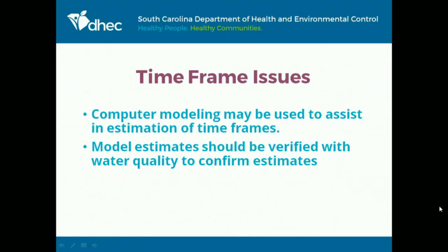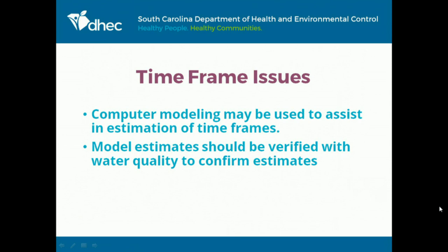Certainly, if you are going to do modeling, I do recommend verification of the modeling with water quality information. So get your model to say that 2 years from now there's going to be 10 parts per million PCE in this well, and verify it.